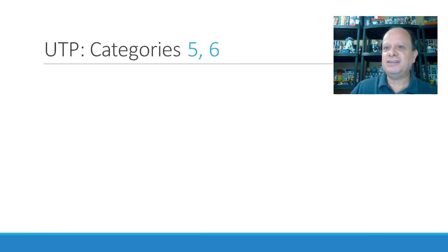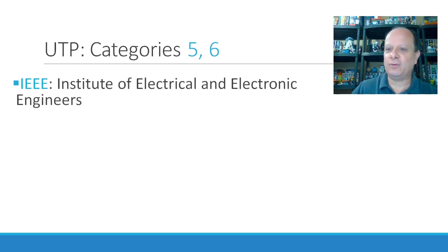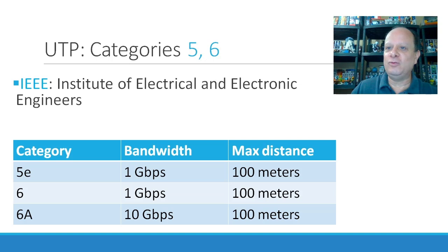The electrical characteristics of copper cabling are defined by the Institute of Electrical and Electronics Engineers, or IEEE. The IEEE rates UTP cabling according to its performance. Cables are placed into categories based on their ability to carry various bandwidth rates. Cables in higher categories are designed and constructed to support higher data rates. As new gigabit speed Ethernet technologies are being developed and adopted, Category 5E is now the minimally acceptable cable type, with Category 6 being the recommended type for new building installations.